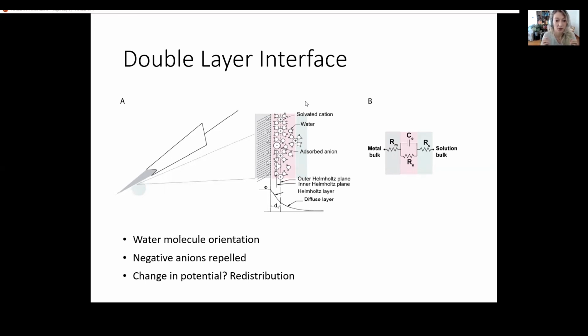For this example, we have a metal electrode. It can be silicon, but it's something that conducts. So if we put our metal electrode into the brain, our metal has a lot of free electrons, and the water in the extracellular fluid, the little positive ions are going to be attracted to those negative electrons, and they're going to orient towards it. What we're also going to see is that negative anions are going to be repelled away from the electrode. So what we get is this interface between the electrode and the extracellular fluid, along which we have very kind of organized strips of charge.